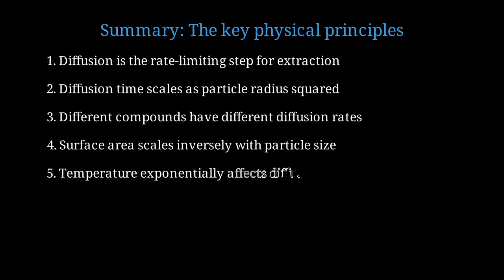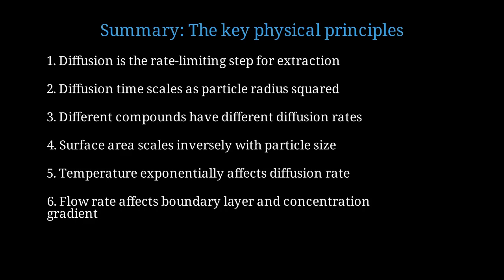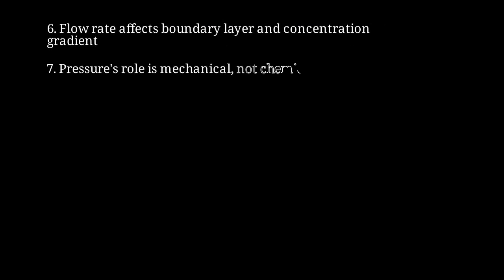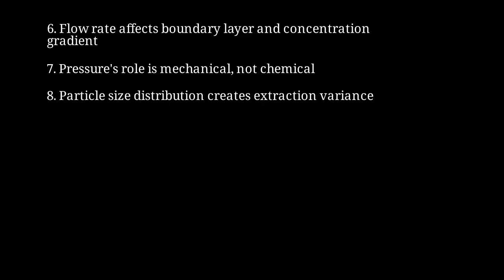Fifth, temperature has an exponential effect on diffusion rate through the Arrhenius equation. Sixth, flow rate affects extraction by modulating the boundary layer thickness and removing extracted compounds. Seventh, pressure's primary role is mechanical, forcing water through the bed, not directly affecting diffusion. Eighth, particle size distribution is critical. Narrow distributions give more uniform, balanced extraction.